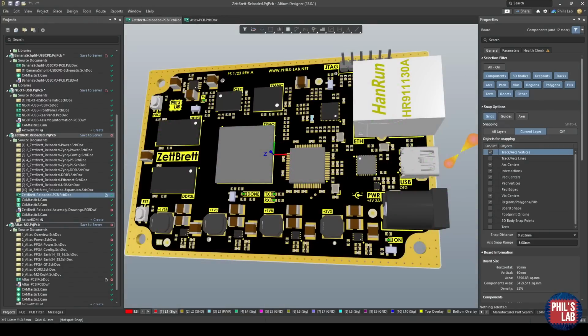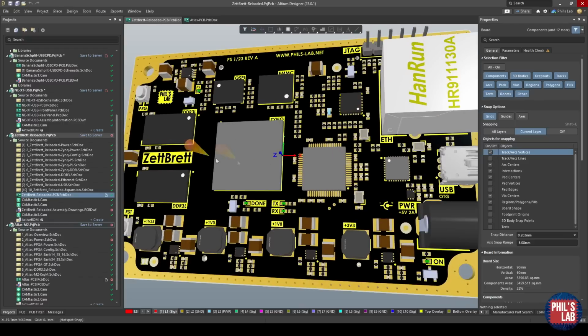Another point I'd like to stress, especially as we're currently still within a global chip shortage, is that you make sure that you have all of the parts you need, at least in stock, or in stock with your preferred PCB manufacturer or assembler, that you know that you can have this board produced, you have all the relevant components. And this is especially true for active components, for example, the DDR memory, or whatever microcontroller or processor you might be using in your design.